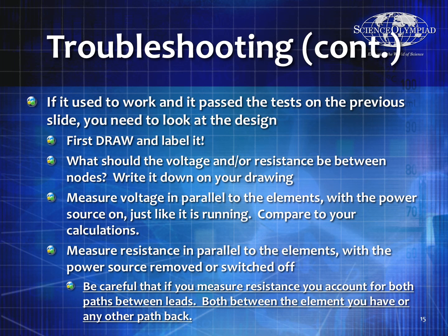So like what I would say is that when I'm measuring the resistance of a light bulb to make sure that it has a resistance, it's not open, which would indicate that it was burnt out, I'll actually remove the bulb and just measure the bulb all by itself, because if I try to measure it while it's in the circuit, there may be another short or something else that I can't see, and the bulb is burnt out, but there's also a short.